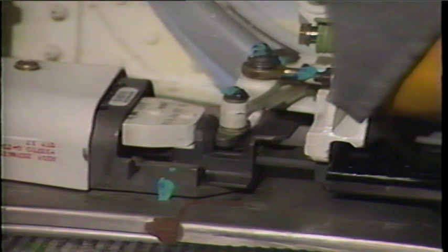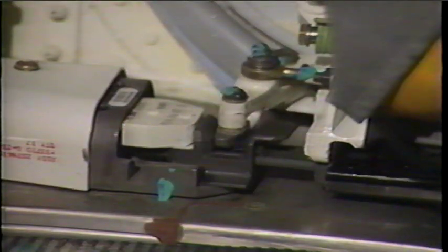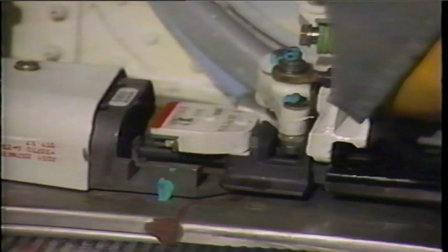Move the mode selector lever to detach and check that the girt bar slider travel meets the minimum travel requirements in the maintenance manual. Operate the mode selector lever several times to be certain the girt bar sliders are operating properly.